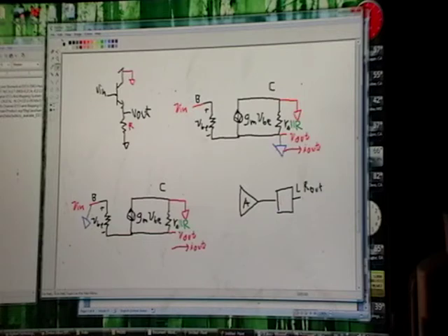Now we're getting the same signal here as we get here. It's just that the R out looks low here, but it looks big here. Okay. So that's great. The way to get the same signal here as here is you don't want the follower here to load your amplifier. So what you need here is a big R in. You want a giant R in, so it doesn't load your amplifier. So let's look at what you need to do there.